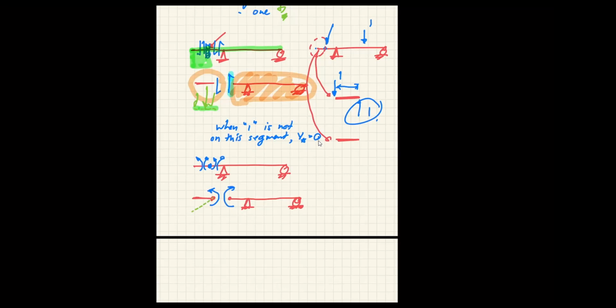Because on the left, this is a free end. So when you have the moment, it's just going to move like this. Just going to rotate, just like opening the door. When the moment is in this direction, so your door is opening down like that. But what about on the right? On the right, you have the moment again, but the portion on the right has the perfect reactions. There are two reactions. So when you allow this moment to move freely, the portion on the right will not move at all.